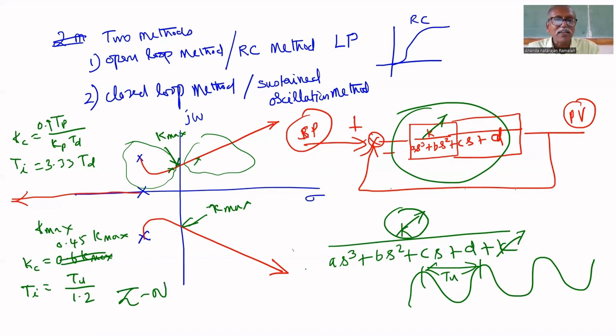They used a 3 to 15 psi signal to transfer measurement. If they measured 100%, they would send 15 psi. 0% measurement meant 3 psi, and 50% meant 9 psi. That signal was used in those days. At that time, the PID controller could be tuned using these two formulas. They gave the thumb rule, this formula and this formula.